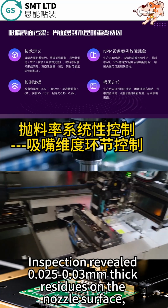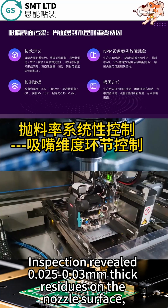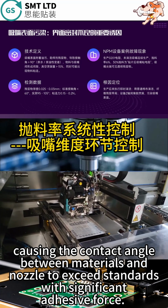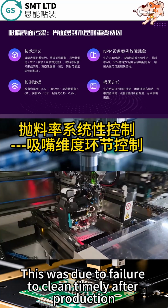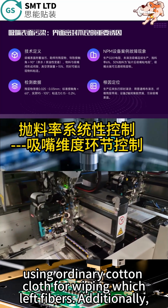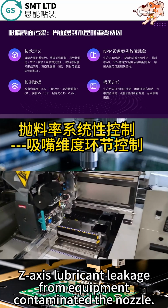Inspection revealed 0.03 to 0.05 mm thick residues on the nozzle surface, causing the contact angle between materials and nozzle to exceed standards with significant adhesive force. This was due to failure to clean in time after production, using ordinary cotton cloth for wiping, which left fibers additionally. The excess lubricant leakage from equipment contaminated the nozzle.